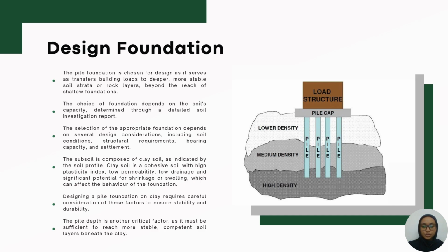The pile type is crucial. Piles are often the best choice for clay as they provide reliable load transfer through skin friction and end bearing. The pile depth is another critical factor as it must be sufficient to reach more stable, competent soil layers beneath the clay.